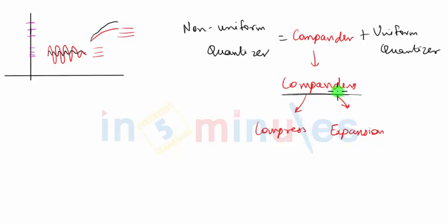You cannot do the companding in any random way because the receiver must carry out the inverse process of companding. Hence, the receiver can design an inverse system only if it has a perfect knowledge of the actual companding system that was used on the transmitter side. And hence, the companding process is standardized with the help of two different types of companding systems.